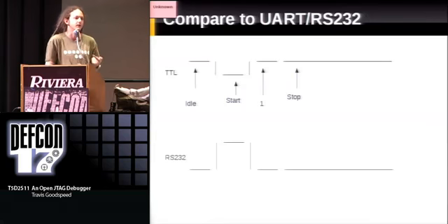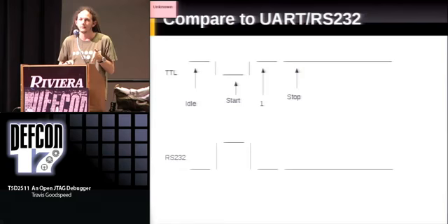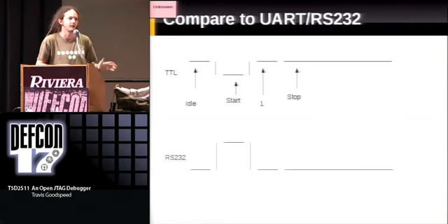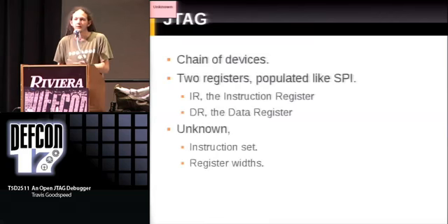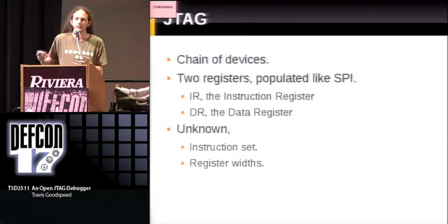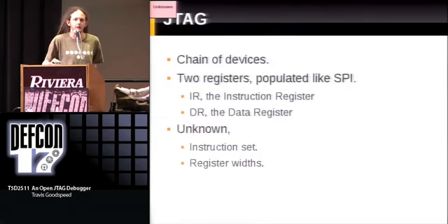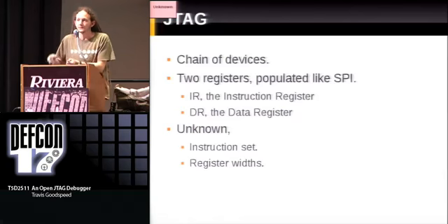But you couldn't really tell where this ended on a scope visually. I mean, you don't know which of these would be 1s. You don't know how wide this is. This might be 5 bits for all you know, or it might be 8. And it requires each device to have a standard clock. So if you remember dialing into bulletin board systems, if you typed in 2400 8N1, that would be 8 bits wide, no parity bit, 1 stop bit at 2400 baud, and you had to know exactly how fast you were communicating.